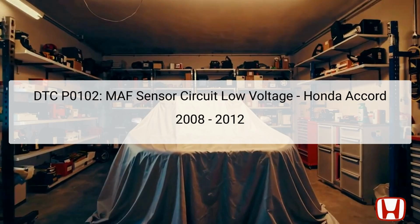This code implies that the sensor is not sending a sufficient voltage signal to the engine control module, ECM, therefore affecting the vehicle's overall functionality. Issues can arise from faulty wiring, bad connections, or the sensor itself. Before proceeding with repairs, it's crucial to record any freeze frame data and run an onboard snapshot for initial diagnostics.